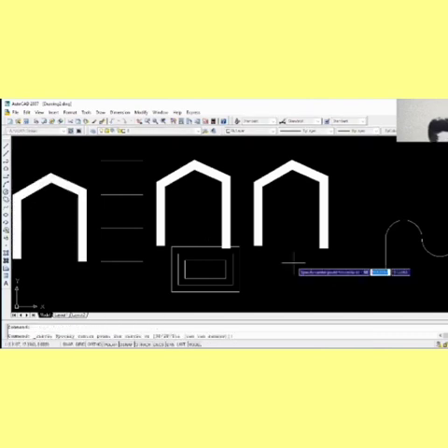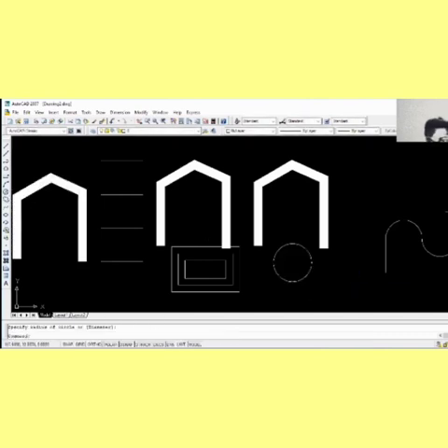You can also offset your circle. You come here. Let's have the circle like this. Now you click on offset. Now you click on the distance. Let's still maintain 1.5. Now you can offset inside, and then you can offset outside. So it depends. So that's about offset.